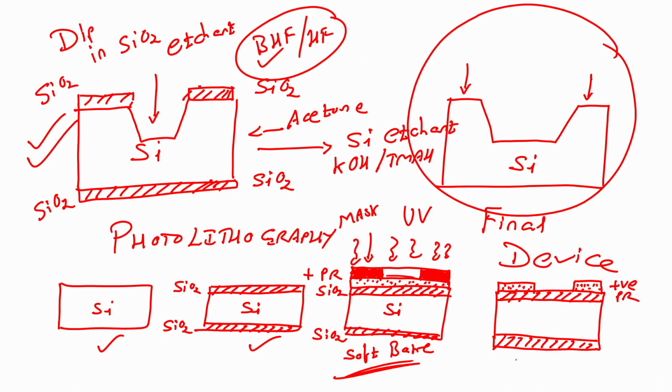After developing the wafer you can do a hard bake. After hard bake I can remove my silicon dioxide, SiO2, with the help of BHF, and